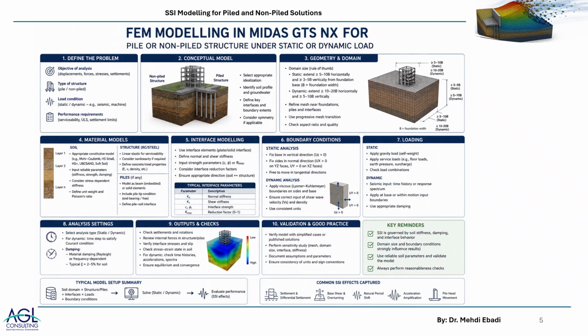Interface is an important element. We shouldn't use interface elements in every project for every interface between a structure and the soil. My experience, at least supported by different field tests, says that, for example, for cast in place foundations, it's better to be cautious in using interface elements in finite element modeling.